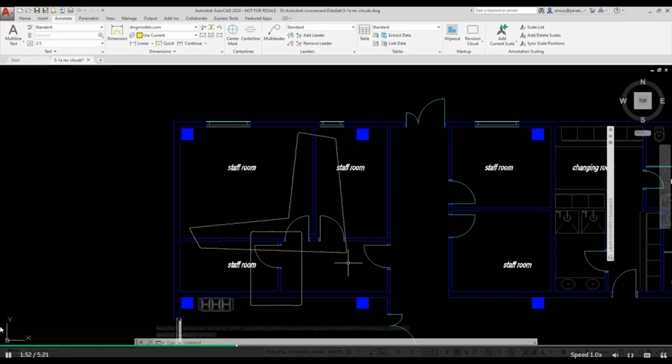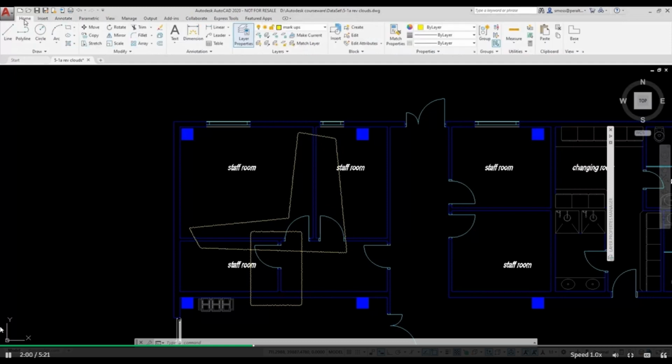I'm going to convert an ellipse to a REVCLOUD using the object method. First, I return to the Home tab on the ribbon and select the ellipse command. I place an ellipse over this wall by selecting a center point and then an end point. I select another point to set the width of the ellipse. I right-click and select Recent Input REVCLOUD.